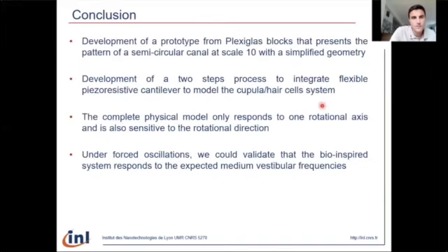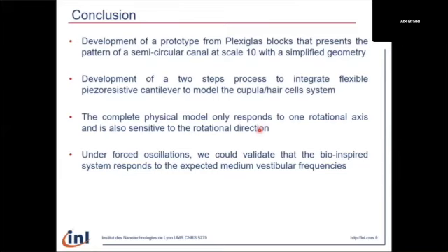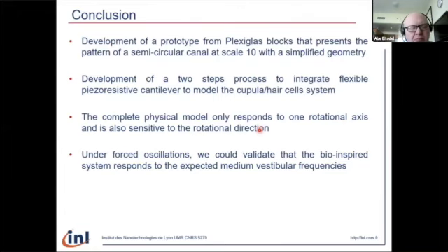So in conclusion, we have developed a prototype from plexiglass blocks that presents the pattern of a semicircular canal at scale 10 with a simplified geometry. We have also developed a 2-step process to integrate flexible piezoresistive transducers to model the cupola. We have also demonstrated that our complete model only responds to one rotational axis, and it is also sensitive to the rotational direction. And finally, we could validate that under forced oscillation, the bio-inspired system responds to the expected medium vestibular frequencies. So now I am done with this talk. I thank you very much for your attention, and please don't hesitate if you have any questions.